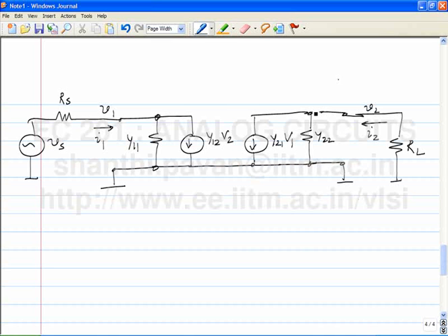And so the next step must be to find the constraints on the Y parameters. How will I find them? First, the thing to do is to find the gain. Clearly the gain will be a function of the Y parameters. What else? Rs and RL. Then we take a look at that expression and figure out what constraints there must be on the Y parameters so that the gain is independent of Rs and RL, and the gain must be as large as possible, and all this other. So in other words, the next job is to figure out V2 by Vs.